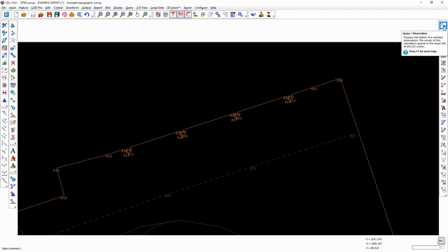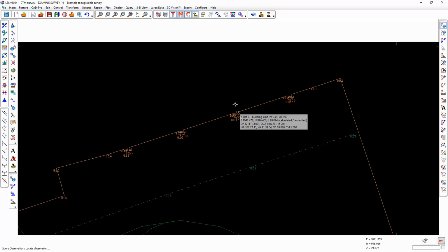And if we're dealing with radial observations, that is angle and distance survey data, then we will retain the angle and distance information together with the link to the surveyed station, but these points will be flagged as amended in the database. It does mean though that if any station setup information or station details or target heights were changed, these points would still move with those changes.